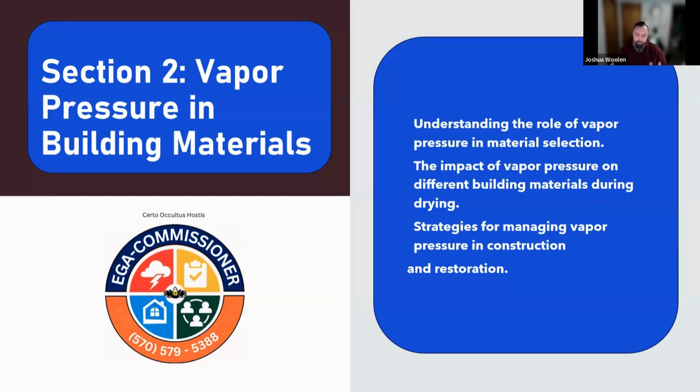So this is why when we come in to dry, we're there to help the building dry itself and retain itself and go back to being what is normal, right? We oftentimes will use desiccant dehumidifiers or LGRs to help set up systems to create this vapor pressure differential so that we can start the drying of the materials, assemblies and contents.